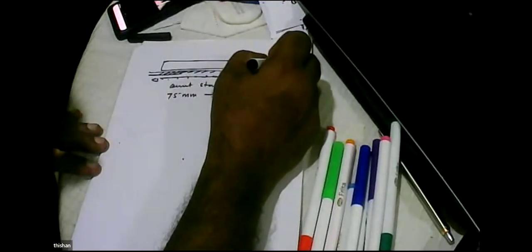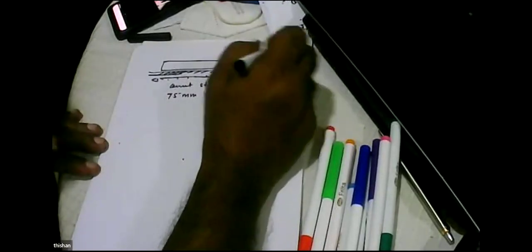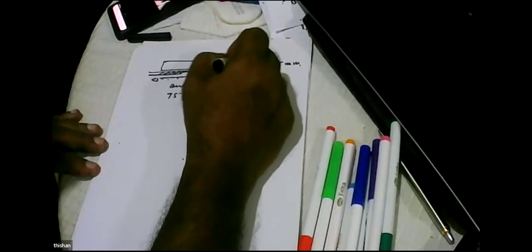But we want it to be perfectly level. Otherwise, our slabs may not have a perfectly level surface. So we have to have a polythene sheet as well. And this is a 45 millimeter tall shutter, 2 meters long. And you can insert the poker vibrator and compact it well.